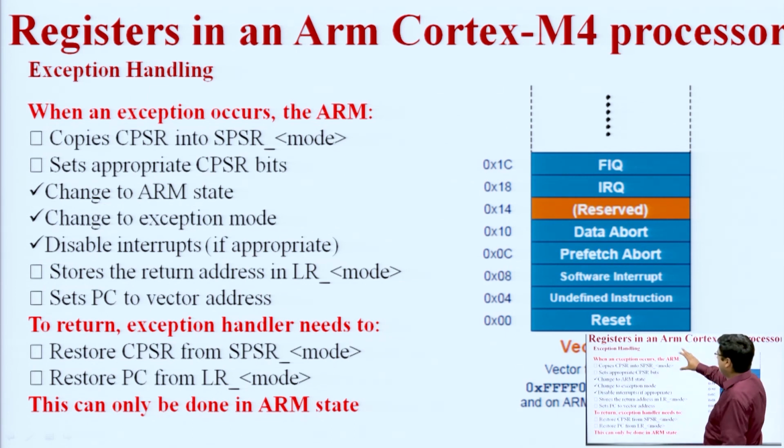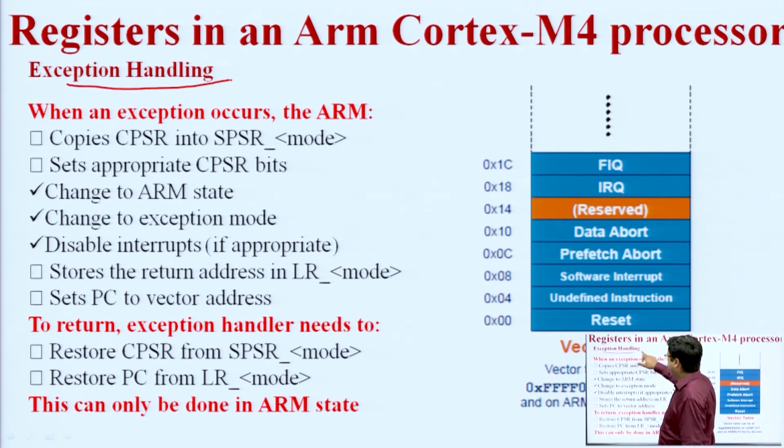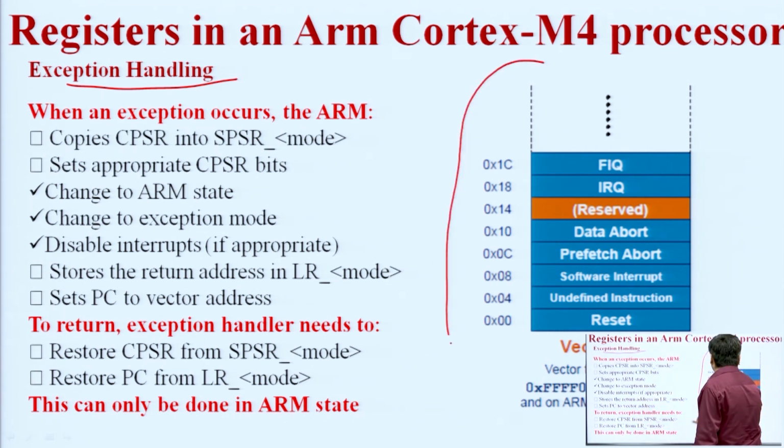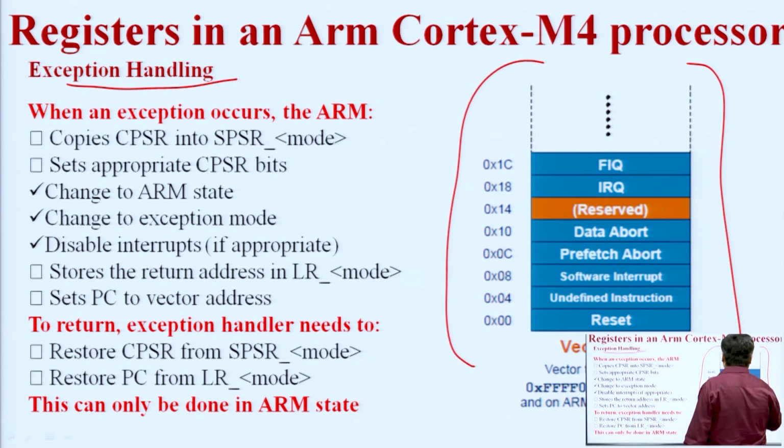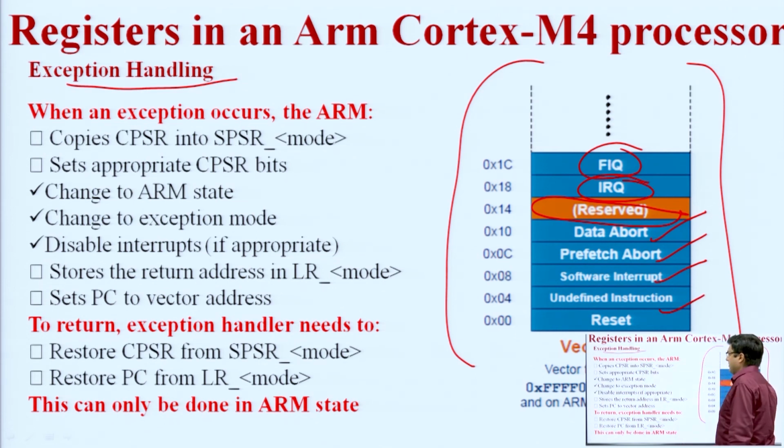In the last topic, we are covering exception handling. An exception means an interrupt, not a normal execution; we are handling the interrupts. So this is the exception model. Here we mention all the modes of operation: FIQ, IRQ, reserved, data abort, prefetch abort, software interrupt, and undefined instructions. All these things are covered here.